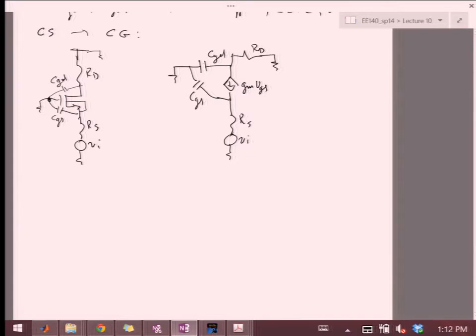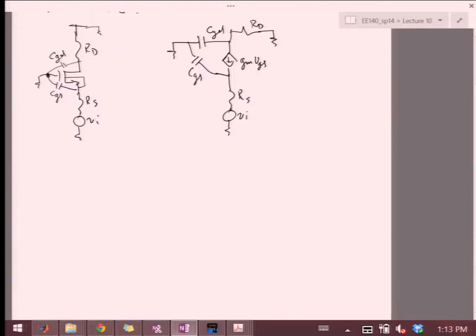If we look at this, I can count the number of capacitors and say, okay, it's two capacitors, there's no loop, so it's roughly two poles. And there's no direct capacitor on the path from input to output, so there's no zero. Then I can analyze it using open circuit and short circuit time constants and try to figure out both of these, and that's what we're going to do. But let's first do the exact analysis just so we know what we're dealing with.